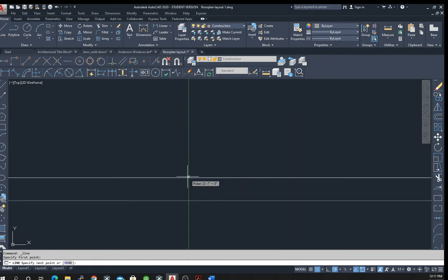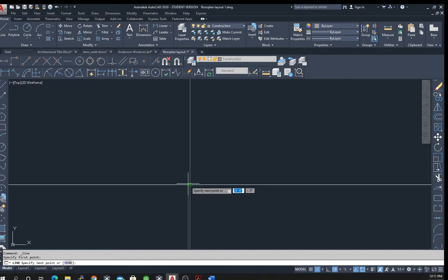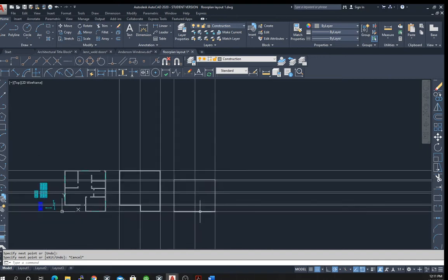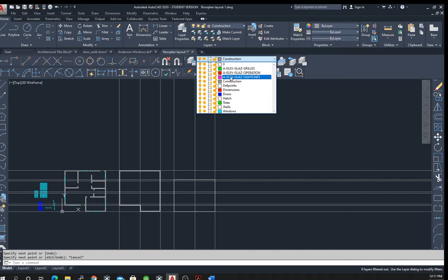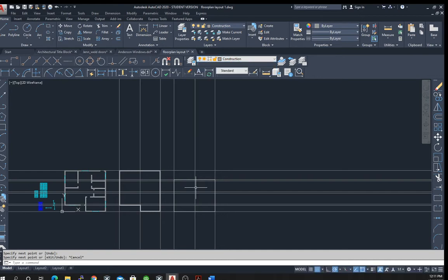And when you have a midpoint near, see, that would be if I ended at the midpoint, but I want to end at the intersection. When you have a midpoint and intersection near each other, then you can run into issues. Okay, so I end the line there. I'm going to turn off construction lines. And again, I did put that in construction layer.